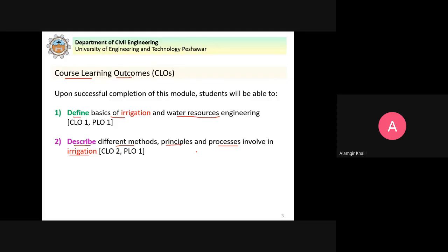Should there be a level crossing where the water joins and is then withdrawn on the other side, or do we take the canal above the drain or stream, which is known as an aqueduct, or below the drain or stream, which is known as a siphon? So you should be able to describe all these.